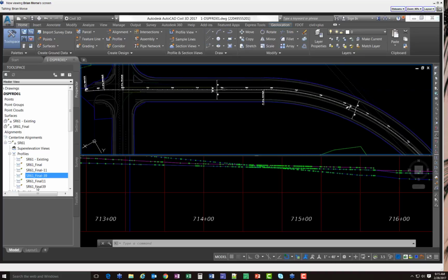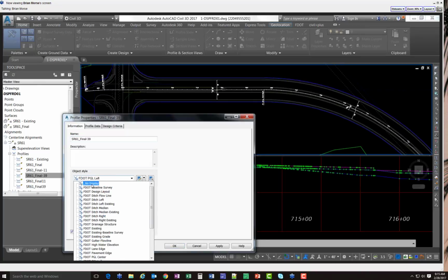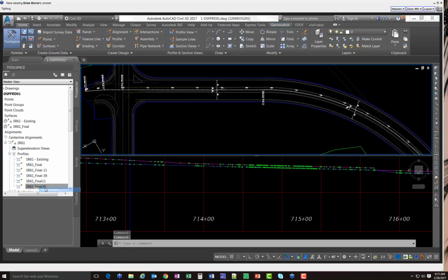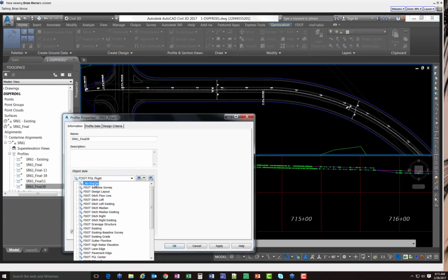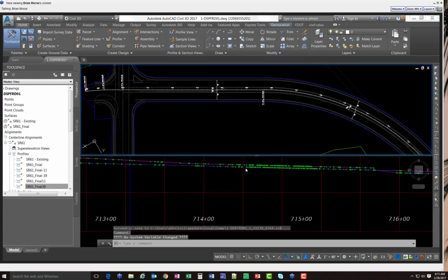The 39s, I think we'd like to change the style on those. Can we change the style right here? No. Description, so very inefficient when it comes to profiles. In other parts of the dialog box here, you can actually gang up your edits on the lower part of this, but profiles, they've been kind of left behind. So what I want to do is just shut these off. I should have done this, but you know, we're going sequentially through the operations, so that way it makes sense.